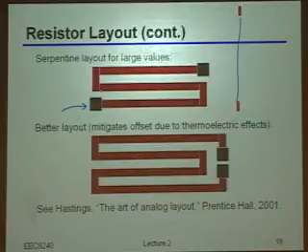Or? Yeah. Is that sort of thing actually typically done in FET? Normally you can actually trim your poly around corners. Okay. So it depends on what technology you're in. There are some technologies where you wouldn't even be allowed to run a polyline vertically versus horizontally. They would all have to be in the same direction. But nobody says this has to be poly per se, right? This could be metal, this could be something else. Even if it is poly, you could put another via or contact there and run the vertical thing in metal. The basic point is more just to say that, if you have really, really large values or really, really large unit elements, you'll tend to probably snake them rather than have this one long, linear kind of thing.